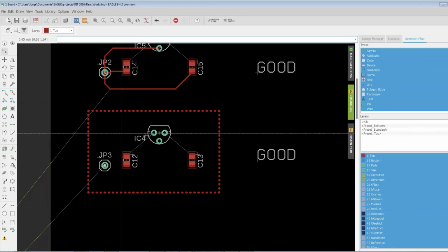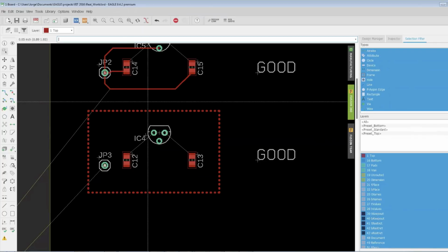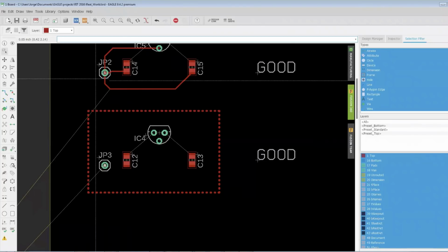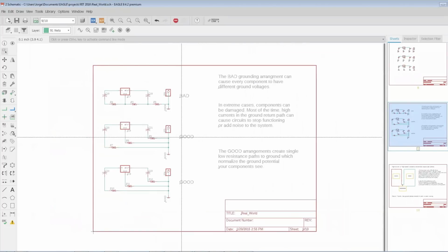So keep that in mind. Okay, think signal path, return path. Don't think so much in terms of a ground. That's going to help avoid issues in the future. Okay, so let's kind of summarize what we've gone over.